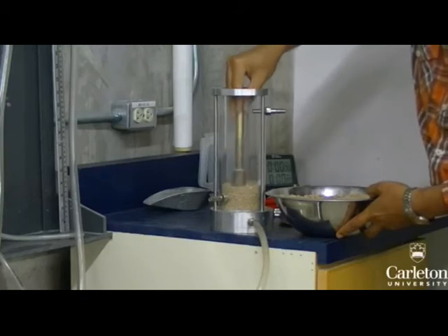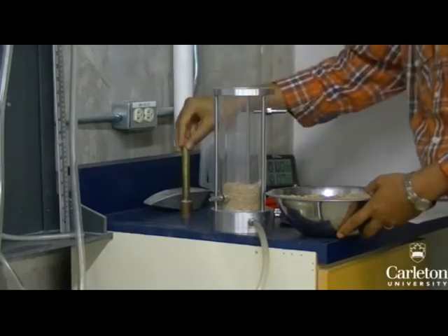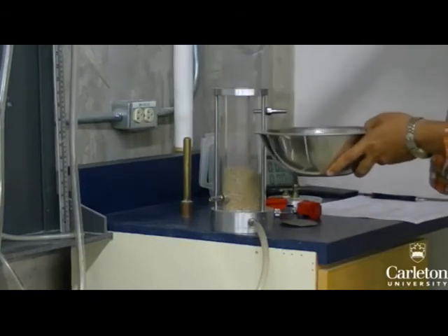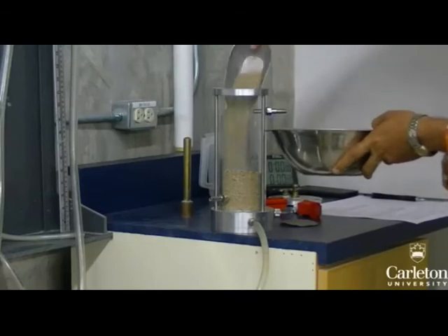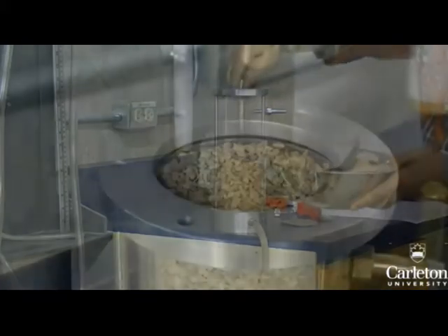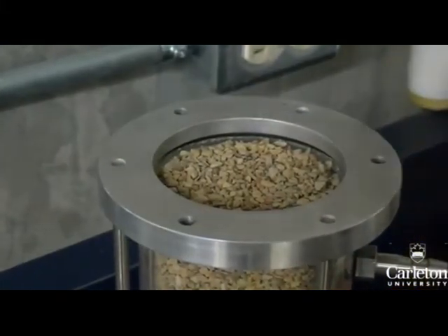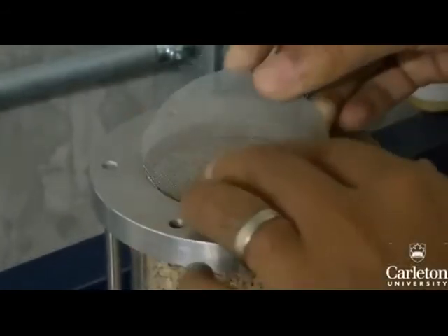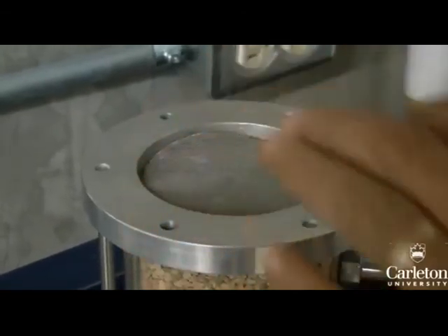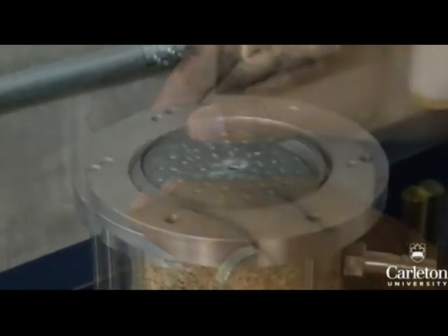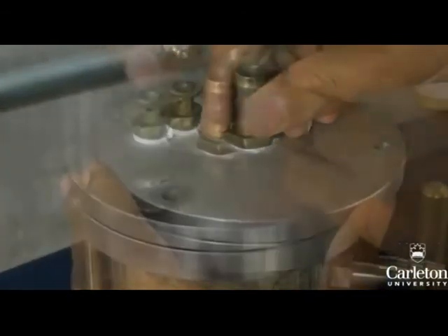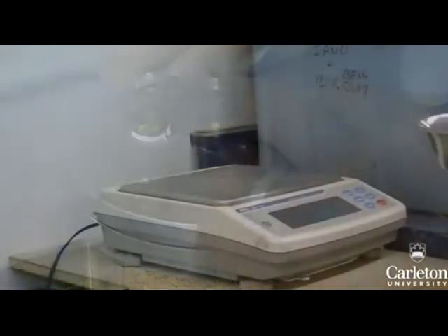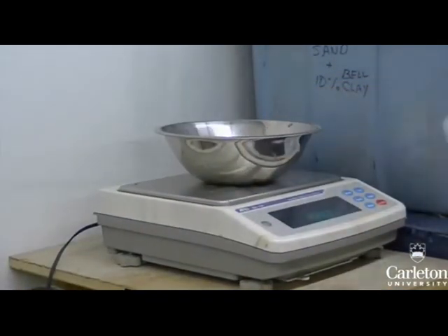If your objective is to determine the conductivity at a specific density, measure the mass required given the volume of the cylinder, and compact the sample enough so that it completely fills the cylinder. The top surface of the soil in the cylinder should be level with a small space for the screen and end cap. Place the screen on top of the soil as well as a separator. Next, place the cap on top of the cylinder and secure it with 3 screws like this. Record the mass of the container plus the remaining soil.